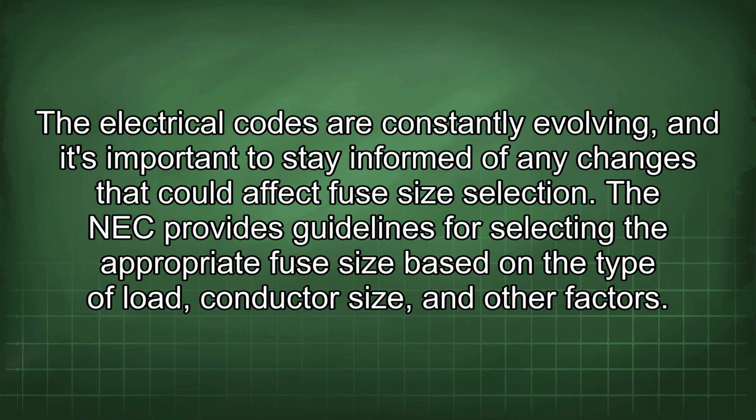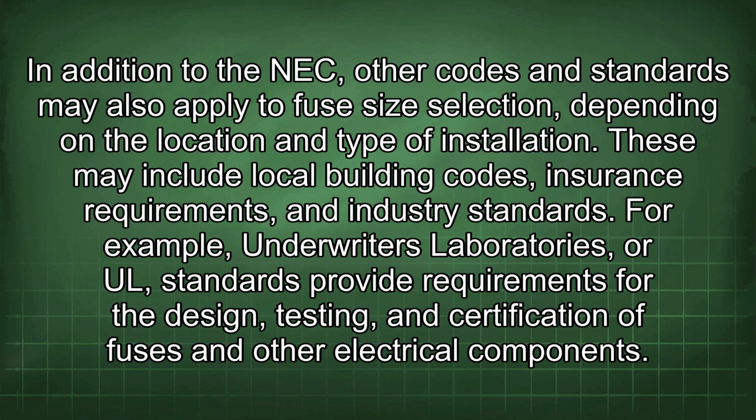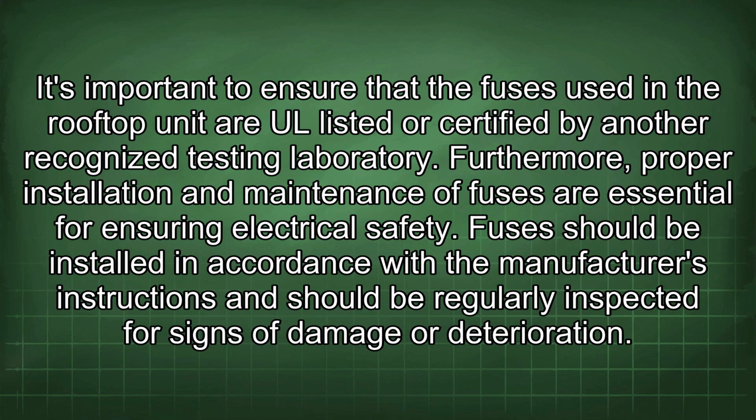In addition to the NEC, other codes and standards may also apply to fuse size selection depending on the location and type of installation. These may include local building codes, insurance requirements, and industry standards. For example, Underwriters Laboratories, or UL, standards provide requirements for the design, testing, and certification of fuses and other electrical components. It's important to ensure that the fuses used in the rooftop unit are UL listed or certified by another recognized testing laboratory. Furthermore, proper installation and maintenance of fuses are essential for ensuring electrical safety.